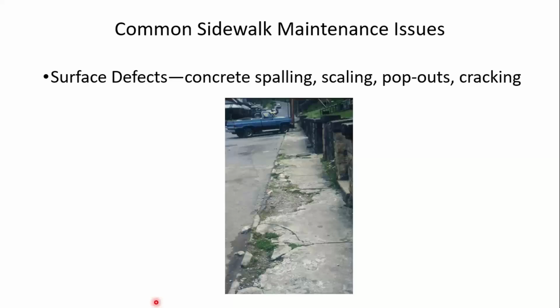And I just wanted to show some of the common sidewalk maintenance issues. Obviously, there's a wide variety of these, but things like surface defects, like spalling of the concrete, scaling of the surface, pop-outs, cracking. Here you see many of those illustrated. This sidewalk, in my opinion, is basically inaccessible. It'd be difficult, if not impossible, for someone in a wheelchair or using braces or crutches to navigate this section of sidewalk.